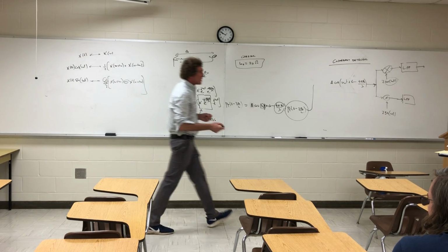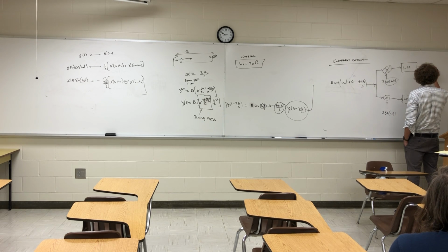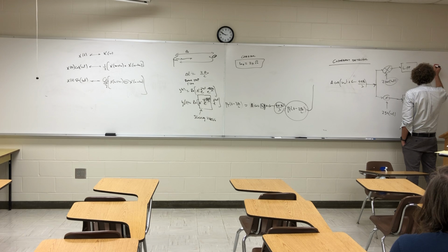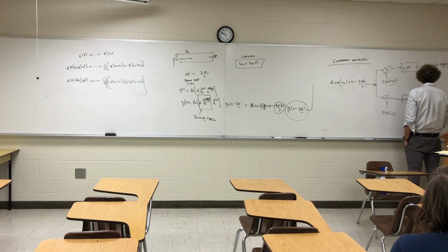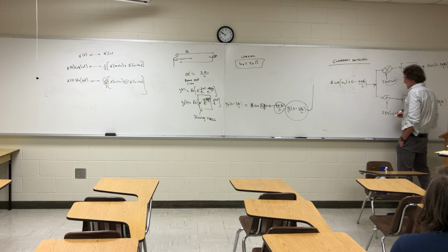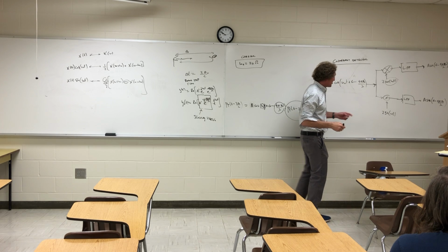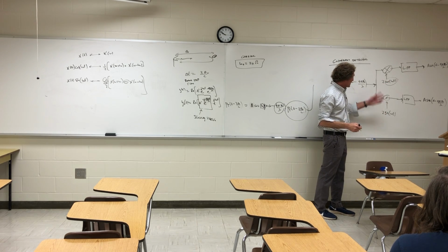And what that means is, when I multiply this by the cosine, the low frequency, then go through a low pass, what comes out is going to be A times cosine, the low frequency components, which is going to be theta plus 4 pi r naught over lambda. And here what comes out is just A times the sine of theta, actually minus 4 pi r naught over lambda. Now, you all see, the only thing we've done is we've multiplied by these things, sine of omega naught and cosine of omega naught weighted by 2.